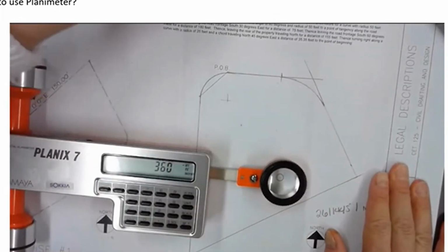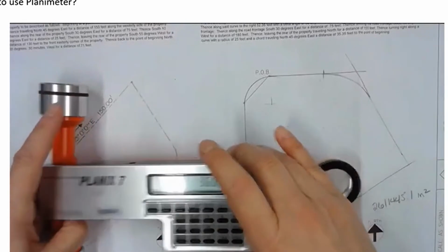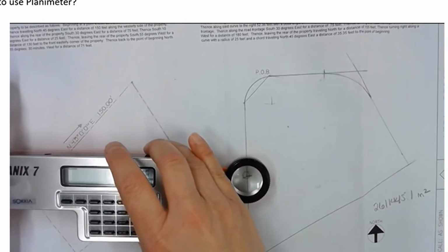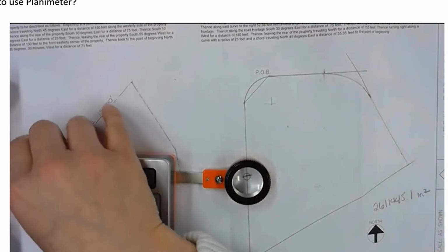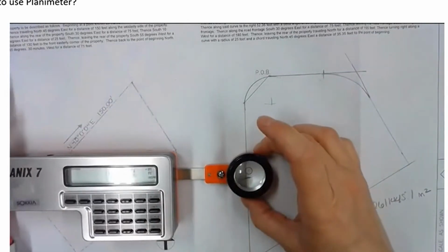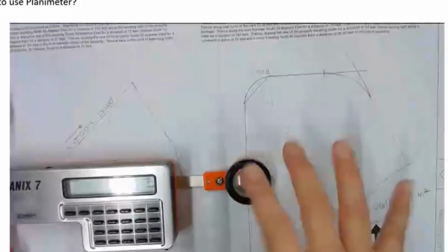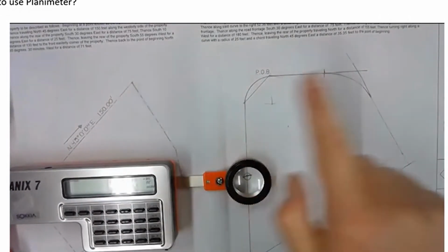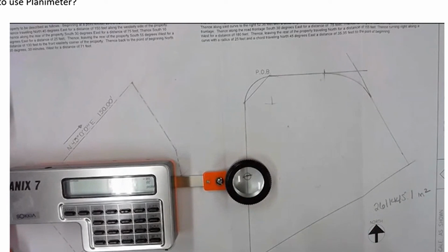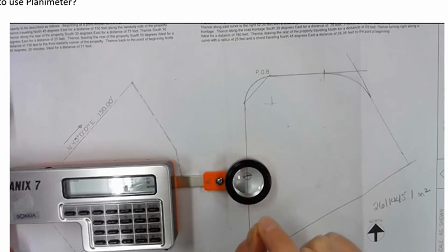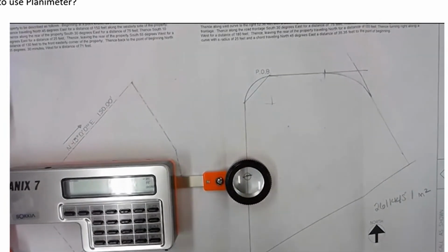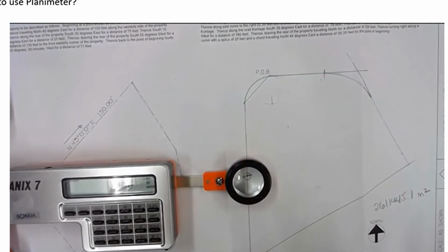Finally, you're going to want to set up the planimeter so that everything is perpendicular and you're going to start your readings so that you can go clockwise around the shape that you're trying to measure. You want to set it up so that the wheels are perpendicular and everything is lined up, about at the midpoint on the left-hand side of the shape, so that you can trace in a clockwise direction. If you try to trace in a different direction, you're going to get a wrong answer. Once everything's lined up, you'll see that there's a little bullseye inside the magnifying glass. It's an orange circle with a little orange dot. That orange dot is what you're going to trace along the line of the shape that you're trying to measure.